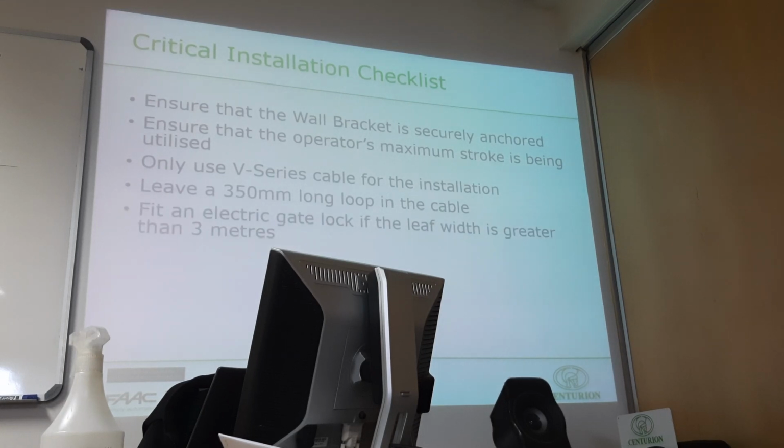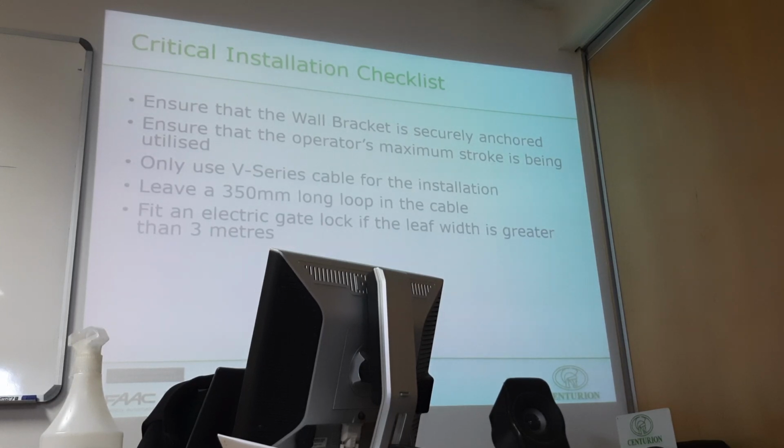Good. And then, if the gate is more than 3 meters in length, try to see, if the client's got money for it, try to sell him and install a gate lock. Because no matter how strong you build your gate, if I really want to, I can push this in and start bending stuff and break it, and I will probably be able to get into your property, especially if there's 2 guys. I say, you pull this one, I push this one, you can get in. But if you've got a gate lock here, then obviously that's going to be a lot more difficult.